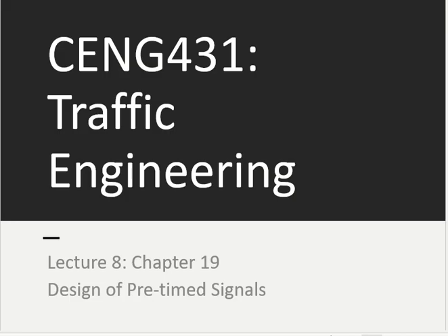The other one is called actuated. Does anyone remember what is the difference between this one and actuated? Actuated means what? If a signal does not have fixed timing, then how does it work? If I don't fix the timing of the signal, then how will it work? By sensors. But those timings which are with sensors are more complicated because you are not designing for one value, you are designing for a range of values.